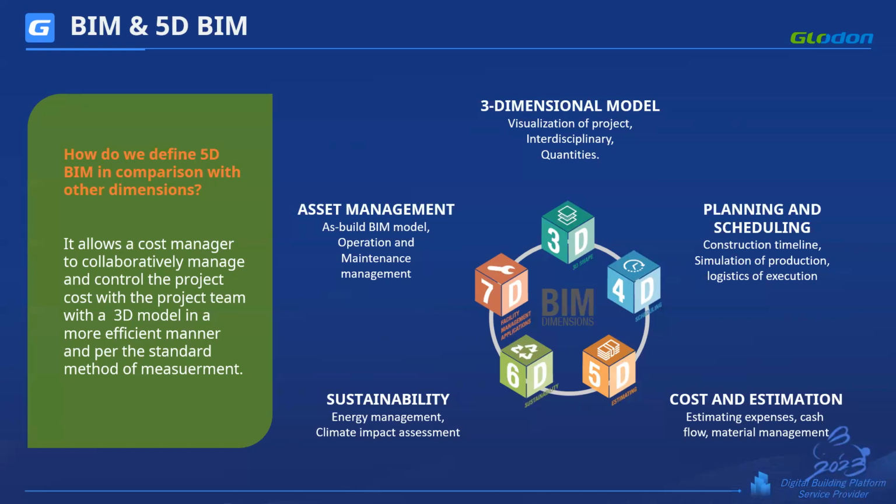If I explain the practicality of 4D BIM, if you have a 3D model, you can merge your 3D model with your construction plan. You can create the 3D model by using software like Revit and ArchiCAD. You can create your construction program by using software like Primavera or MS Project. Then you can synchronize those two software. Then you can simulate your construction project.